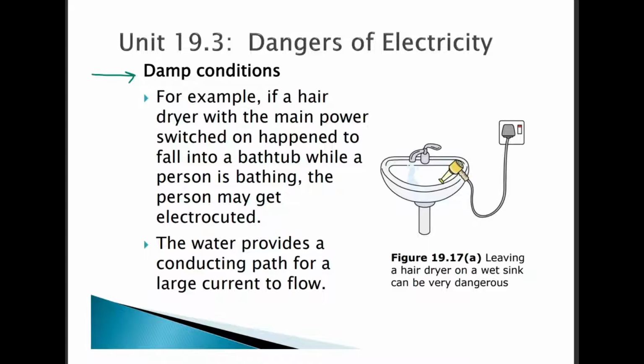The better way would be to first dry your hands, wear some shoes to increase the insulation, or at least have more resistance with the ground, and then you may be good enough to operate the appliance. But then again, it is not advisable. It is just a necessity condition that's possible, but not advisable.